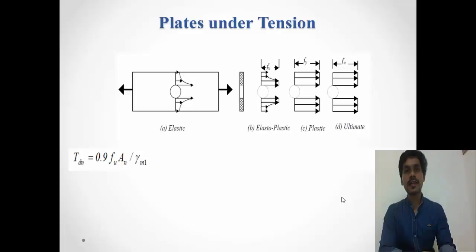The ratio of the maximum elastic stress adjacent to the hole to the average stress on the net cross section is referred to as the stress concentration factor. This factor is in the range 2 to 3, depending upon the ratio of the diameter of the hole to the width of the plate, normal to the direction of the stresses, as shown in the figure.